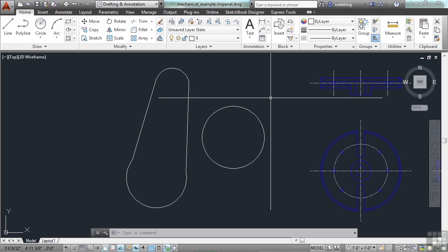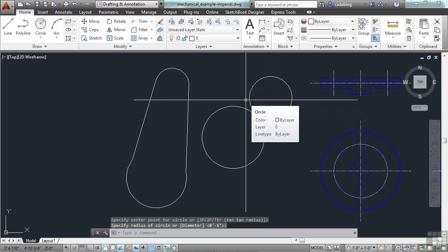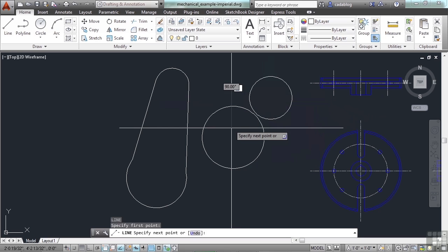Typically though, you'll be able to just enter in your command. Type it in, just start typing wherever you're at. And when you're done, press enter. That starts the command. Another option besides the enter key is the space bar. The space bar in AutoCAD, unless you're typing in text, functions just like the enter key. So when I'm starting a command, I can press space and that's enter. I can start my command, pick a point, do things, and press the space bar.